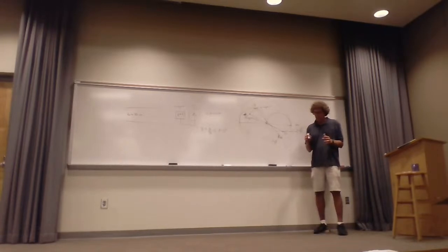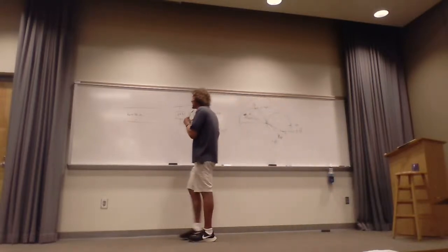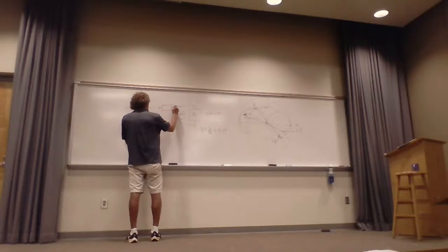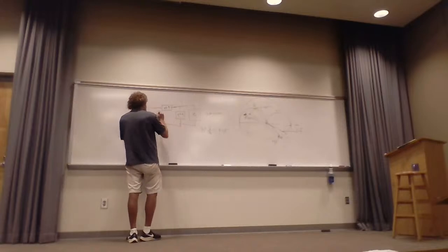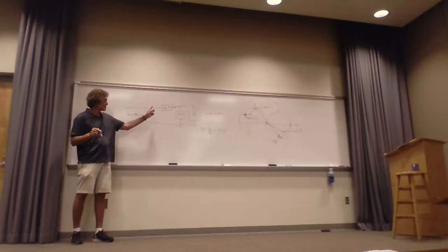Right? 1 minus j3. Well, that's normalized impedance, right? I need to add a plus j3. I know that's going to be an inductor. So that means over here, I'm going to have a series j0.3, and then I'm impedance matched. Got me? Now remember, those are normalized.